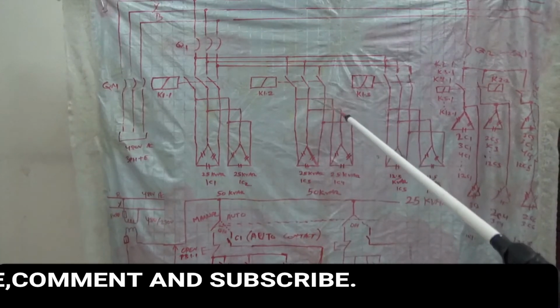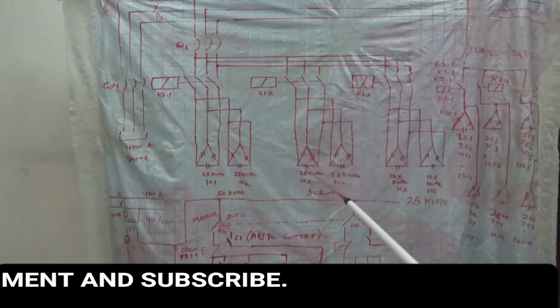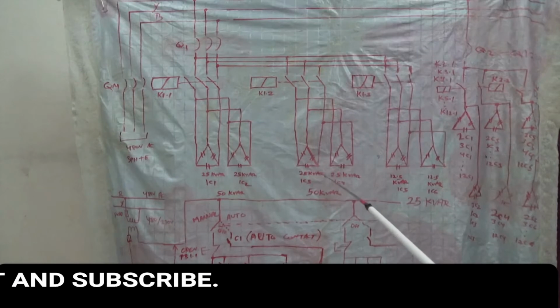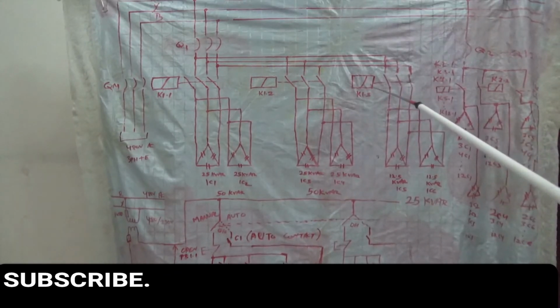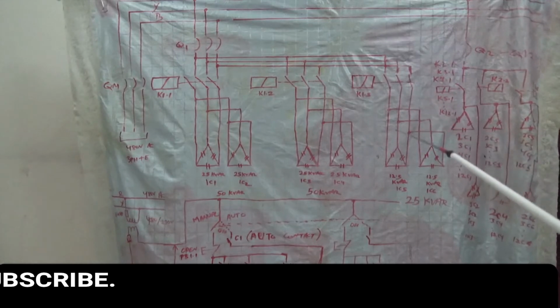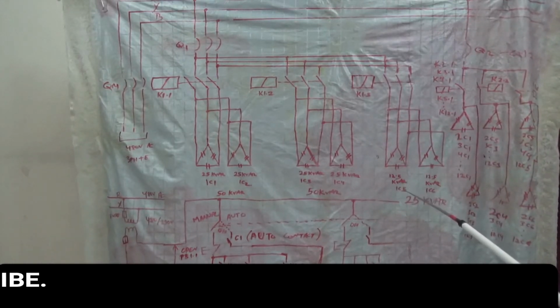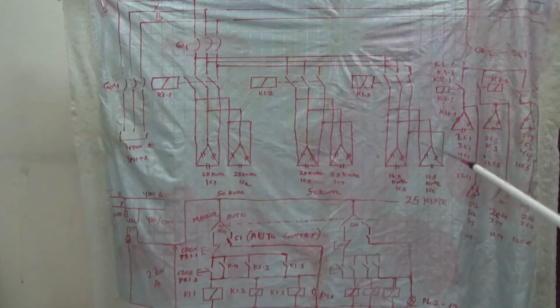The second set is K1.2, and it is feeding 1C3, 1C4, 25 kVAr each. The third set is K1.3, and it is feeding 12.5 kVAr capacitor banks on each contactor. The designation is 1C5, 1C6.